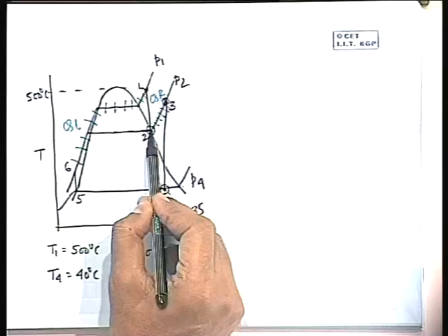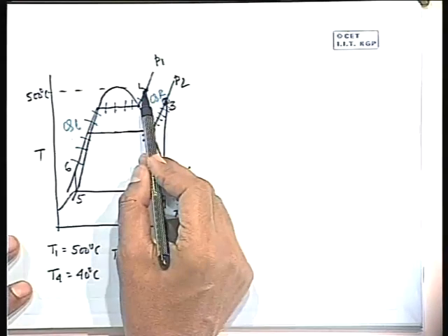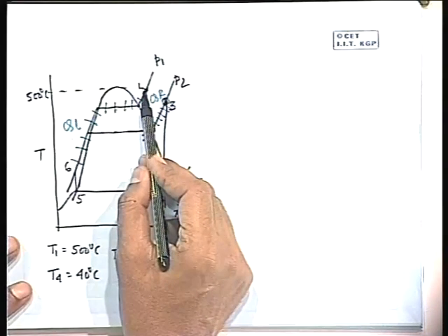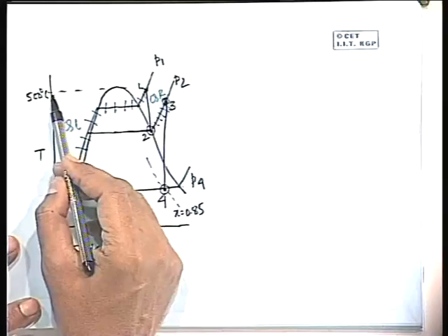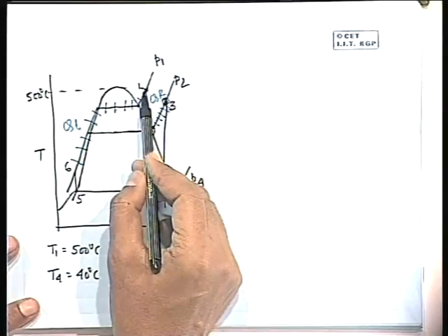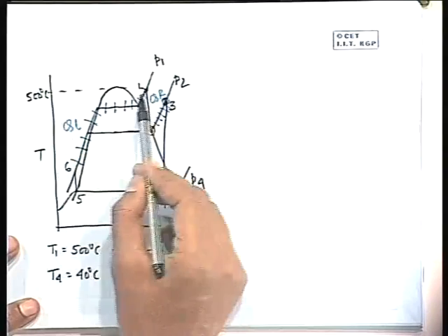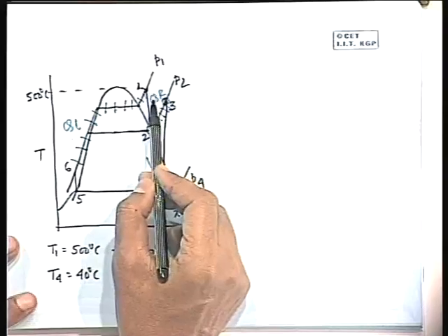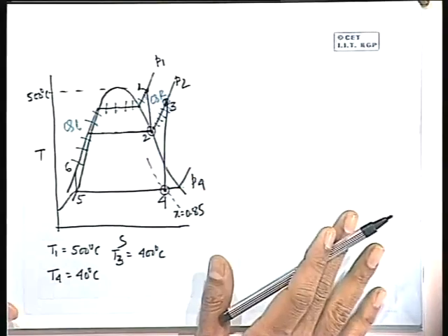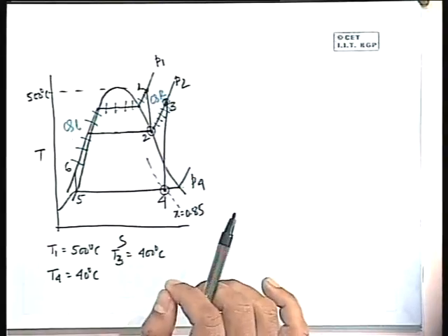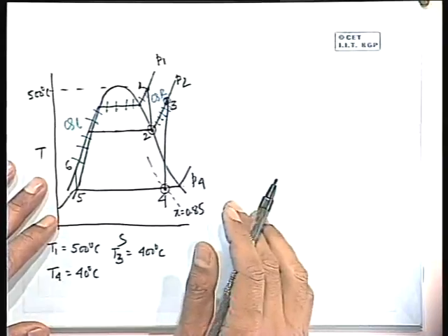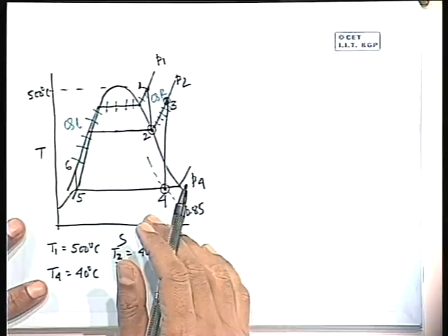If you have any difficulty, you tell me. Then you set S2 equal to S1. Obviously, then you find from the steam table at which pressure, for the superheated steam at 500 degrees Celsius, gives this entropy. So geometrically things are very clear, but to find this from the steam table you may have to do a little trial and error, which will be a little difficult.